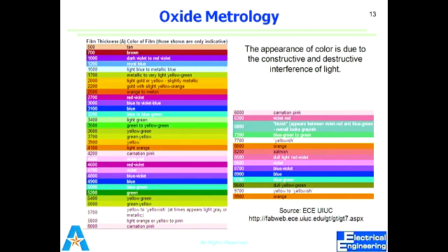As the oxide gets thicker, the color keeps changing; for 1200 there is royal blue, and for 1500 there is light blue to metallic blue. Mostly in our case, our wafers would have this much thickness, 1200 to 1500 angstroms finally. So finally the wafer should have this color, light blue or royal blue.